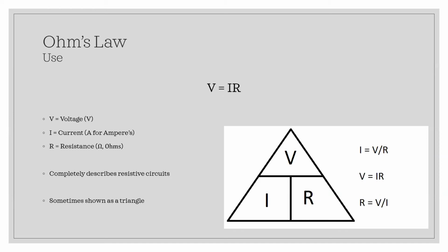So it's very important to remember that voltage is the potential energy between 2 points and not at a single point. If you measure the voltage drop across a wire, there's no resistance, so you're going to get 0. And if you try to measure the voltage difference between the same point, it's going to give you 0. It's not meant for that. It's for between 2 points that have some resistance between them.